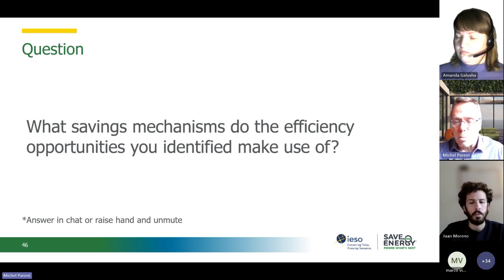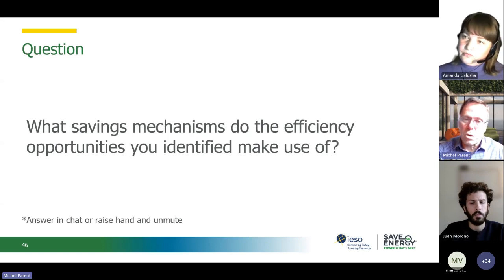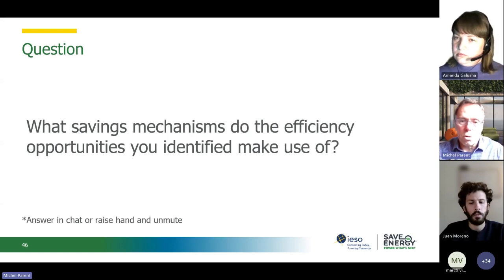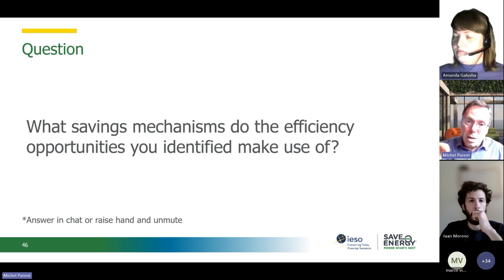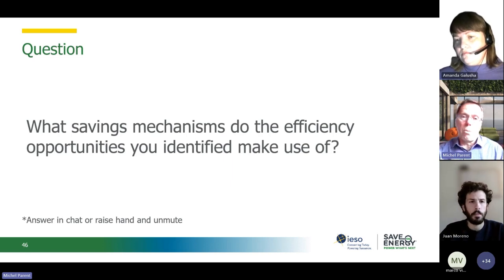You would usually have a minimum runtime, let's say 45 minutes or an hour, so you don't short cycle your motor. But you can do it with a BAS without having a VFD. If you have a VFD, it makes it easier. It's not as hard on the contactors because you don't start and stop, but you've got to be careful. If you stop, make sure you've got a good dead band so you don't short cycle and you have a minimum runtime for your equipment. Then the BAS can do it without investing in a VFD.